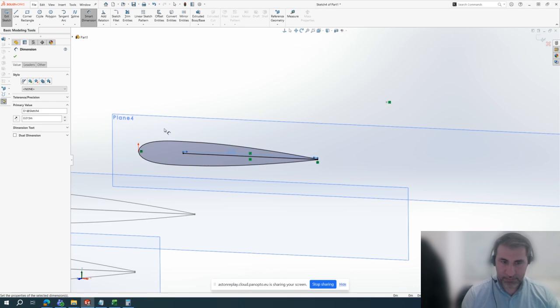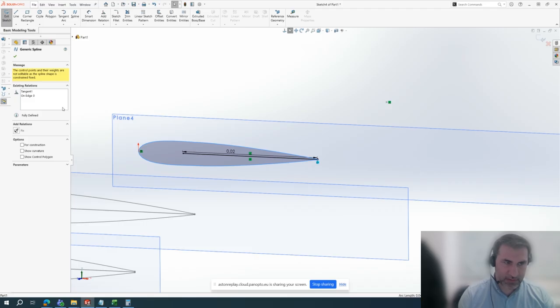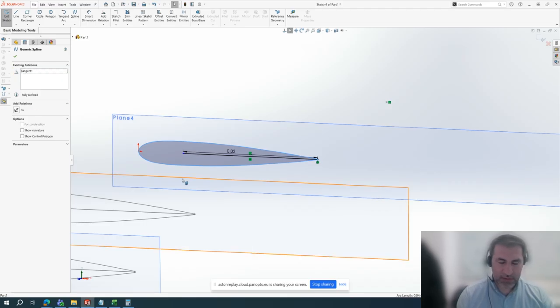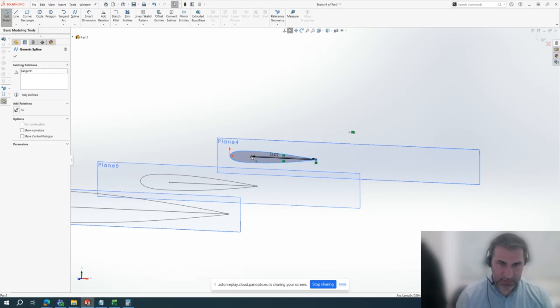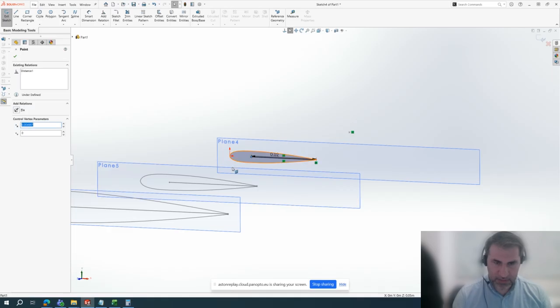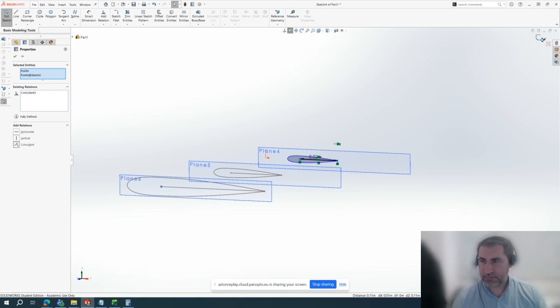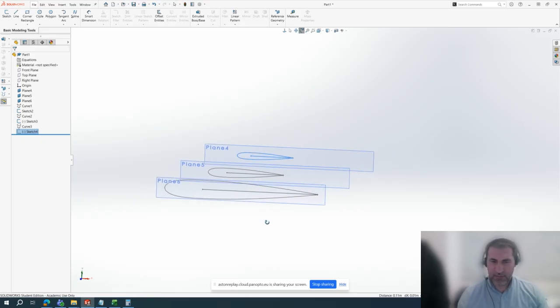That's what I want. In order to make this movable, I need to double click here and remove on edge. Now it's movable. Now in order to make sure the aerodynamic center is the same here, I can click on this. Oops, let's first escape, then hold Control, click on this, and then click on this and say they are coincident, so it moves. Great. So now I can close sketch editing.